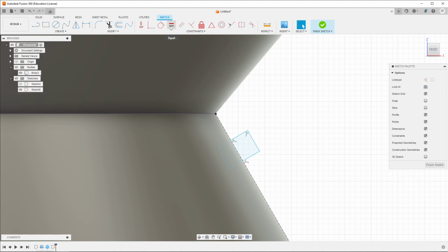So if we look at our constraints, I can use the parallel constraint. If I select this one, there it is. You can see they're parallel. I don't know if it's going to help if I use the perpendicular constraint. It's kind of unnecessary because this is parallel, and this is a right angle, which implies that these are right angles. So there's no need to actually do this perpendicular constraint.